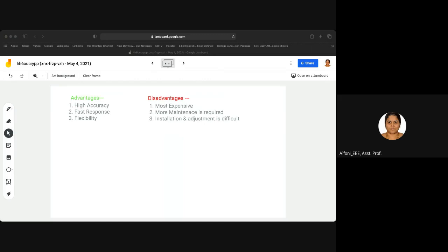And if any fault occurs in the instrument, that leads to a faulty error signal. It may occur due to an open circuit or short circuit in the inner circuitry. So, in such cases, fault location becomes difficult and it takes more time for maintenance. And coming to the maintenance, only persons who are trained in that related field can do the maintenance of this closed loop control system.